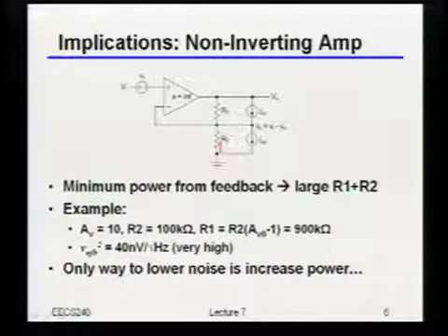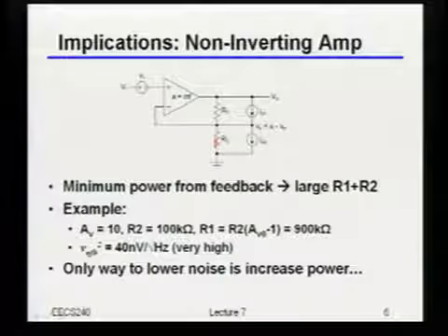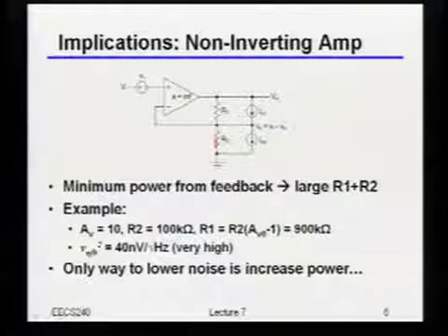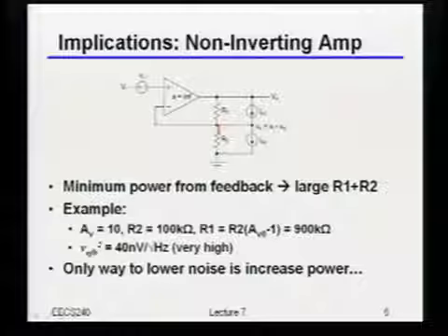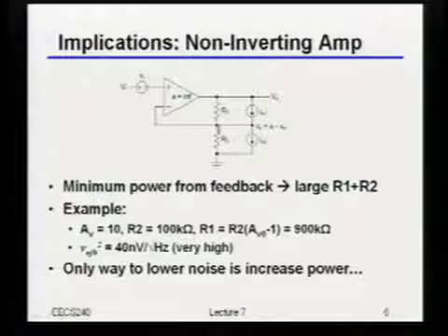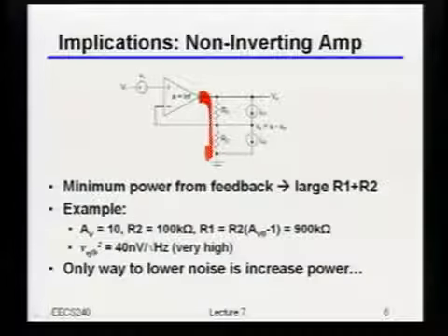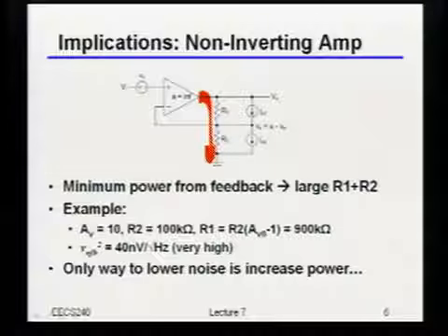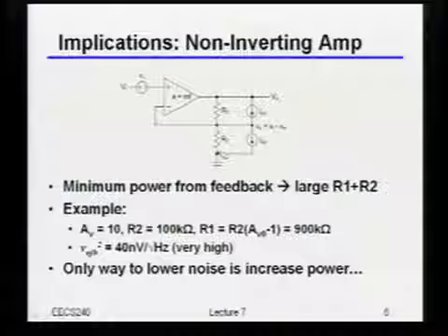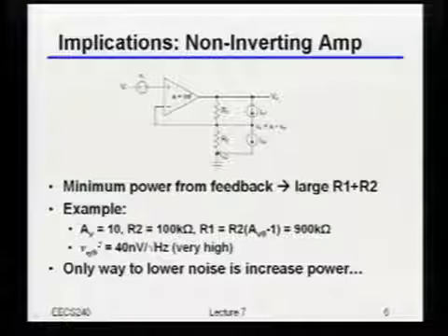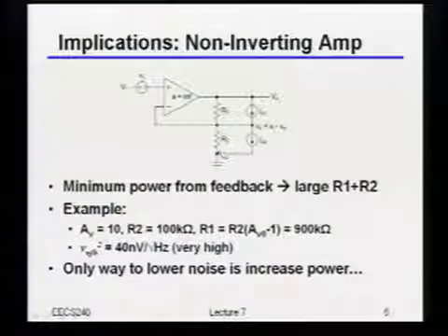So if I wanted to do a low power design, I would try to make these feedback resistors pretty large. By the way, why do I say that? Why do I not want to make these really small resistors? Bias current. Yeah, I'm basically spending current to drive those resistors statically, right? So I want to make those large just to minimize the amount of current I have to spend to create that feedback loop, okay?